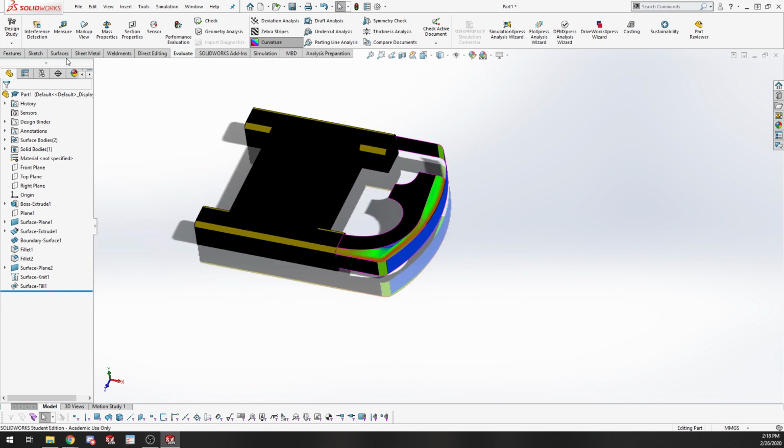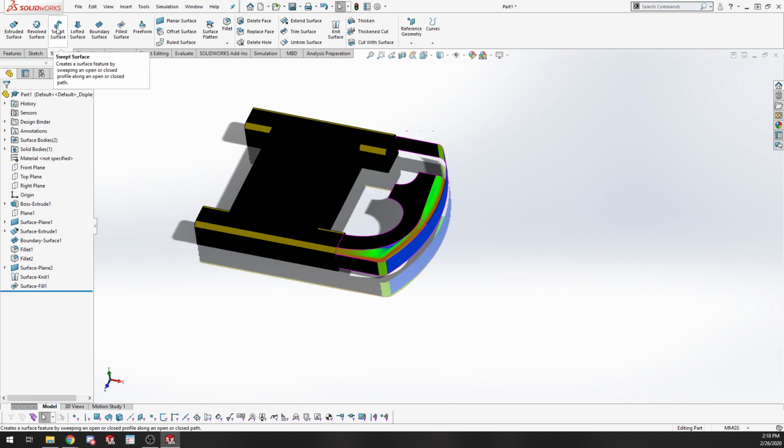All right, so that's most of the surface functions. Extrude and revolve work the same way. It's just you're not filling in that area inside. You're just extruding a constant cross section or revolving a constant cross section. Swept surface, like we were talking about last week and the week before, is just creating that thin feature. We were thinking about the piping, making that, except instead of actually having thickness on that, you just have the outside edge. Loft surface is the same as a loft.